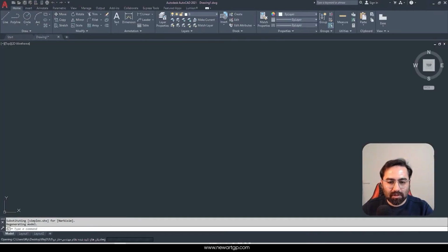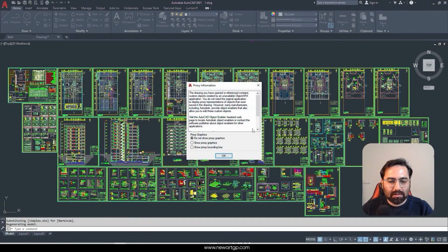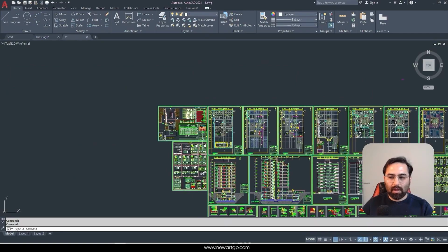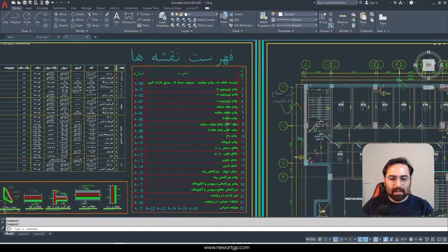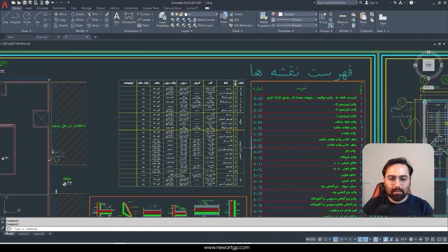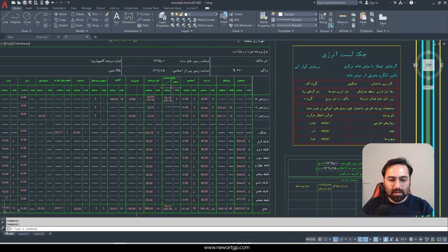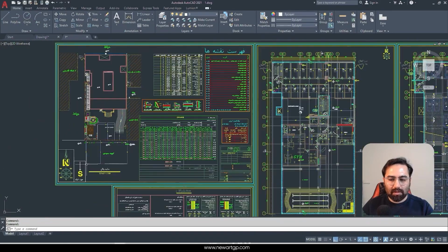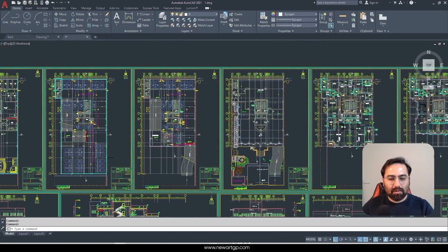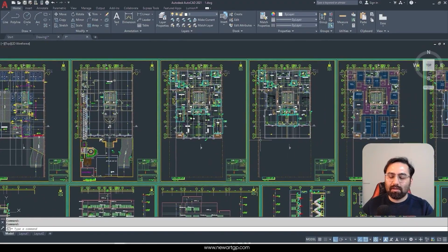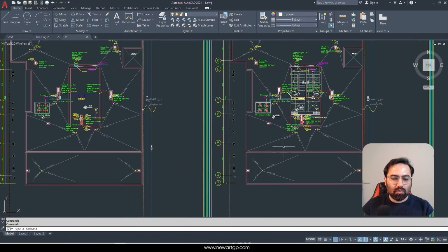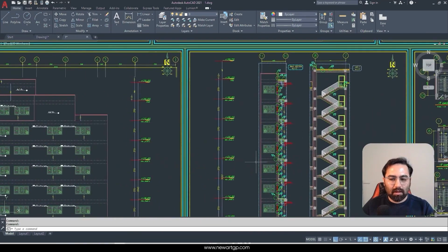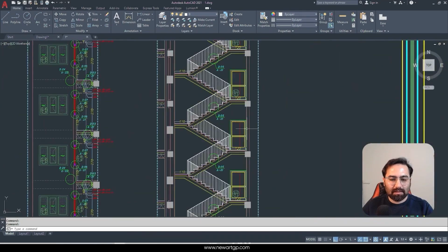So imagine you have a project. In the end, you prepare a set of sheets and print out that booklet. It consists of a set of documents like this, where there are some explanations about the plans, a list of drawings, a finishing schedule, then other plan information, a checklist, energy, maybe a title where the owner's name is written, the site plan, and the north arrow, and so on. Then there's the plan, the reflected ceiling plan, the furniture layout, dimensioning, phase 2, shape layout, and various details of the ceiling, column connections, structure, sections, staircases, and many other things.